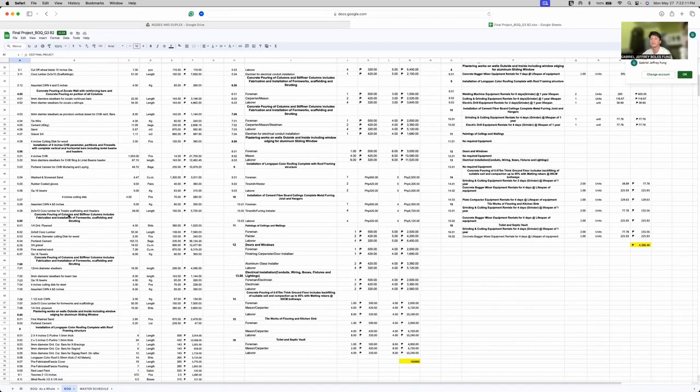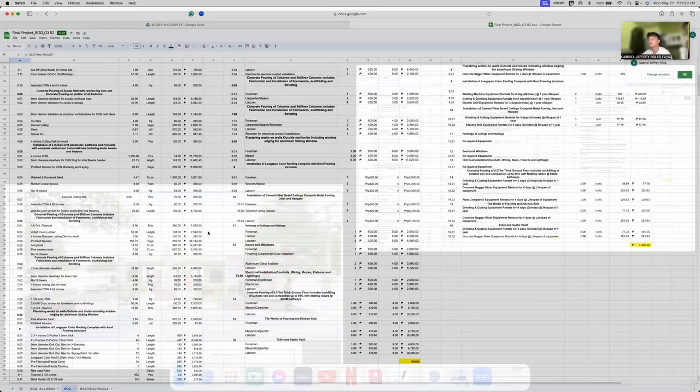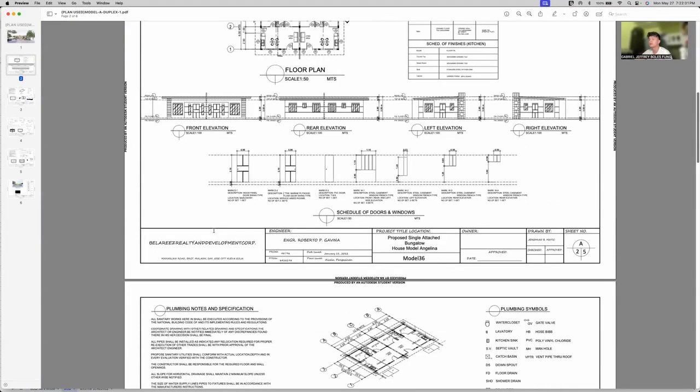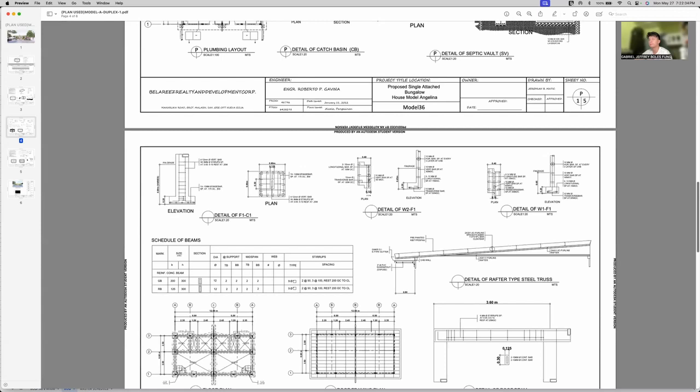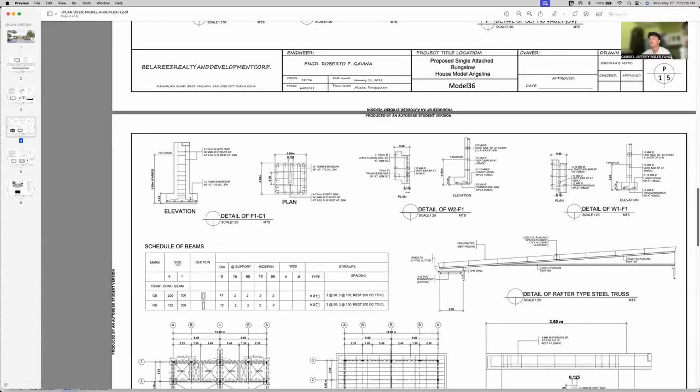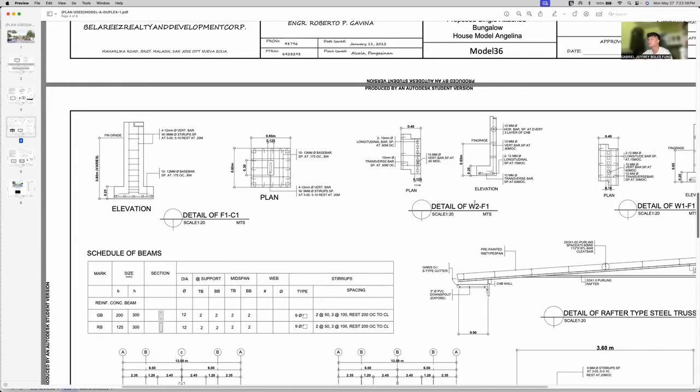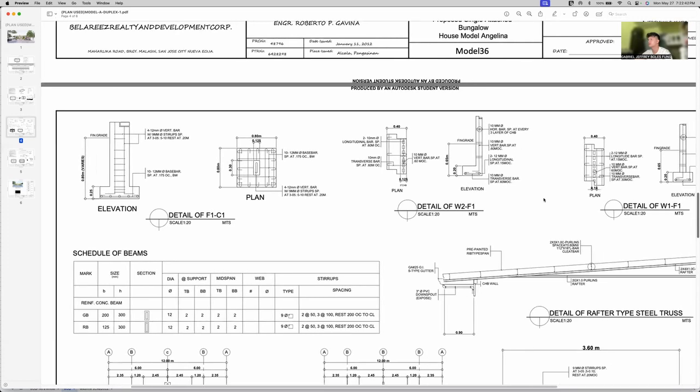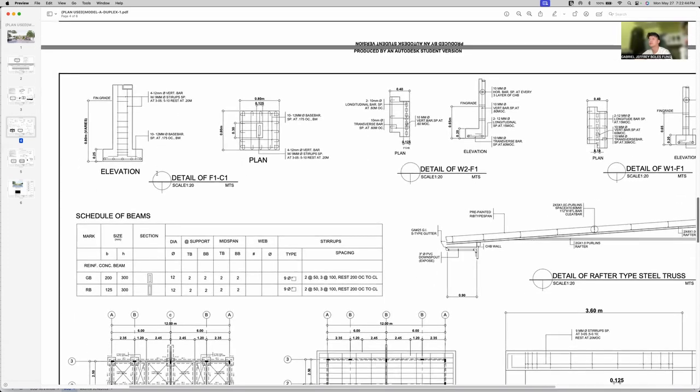So for section 6, it includes plywood, coco lumber, 4 inches diameter cutting discs for wood, Portland cement, 3/4 gravel, fine washed sand, and then gauge 16 tie wire. So similar to the discussion in class, the thickness of the column is given here, in the detail of F1C1, as well as wall footing columns and other details. So primarily we are going to use F1C1.